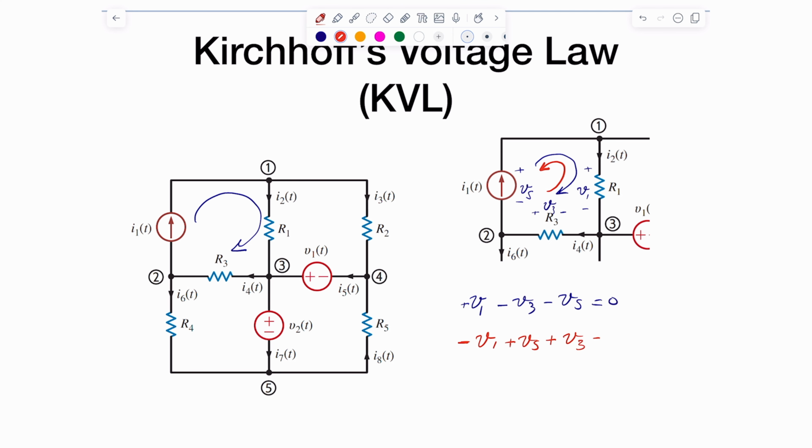If you take a look at these two equations, you'll see that they're algebraically equivalent. You just multiply by -1: the positive becomes a negative, the negative in here becomes a positive, and the negative in here becomes a positive. They're the exact same equation, and that's KVL. So you can write this across any loop you like. It's exactly the same procedure: you define a loop, you sum the voltages around that loop, and you get the equation that you can use in solutions.